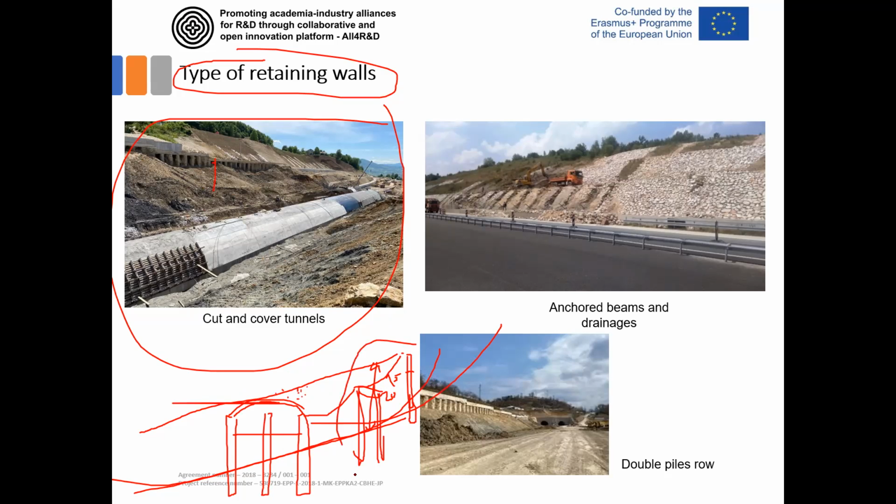So we have some piles that support this temporary excavation, and after you fill this, you can fill it with this to support it in total. So it's relatively complex even to reach this level, to construct these 3 rows of piles, and then you construct this arch, and then you fill it with this excavation material.